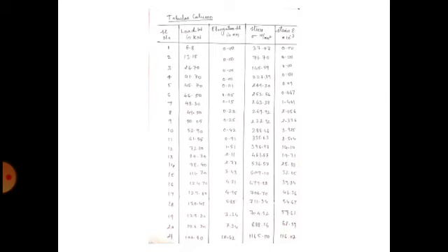45.70 is the load, 0.01 mm is the elongation, stress induced is 249.20 and strain is 0.09 into 10 raised to minus 3. We can observe that the maximum load is 130.45 kilonewton. At that time elongation of specimen is 5.85 mm.